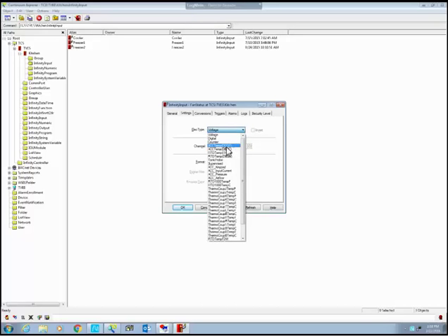A room temperature, if you want it in degrees Fahrenheit, and it is a type 3 10K ohm thermistor, you will choose the ACC temp degree F, and that should be fine for most all these thermistors that you get. I don't use counter so much. I know what it's for, but we'll get into that later. But if it's just an on and off point, you will choose digital. Okay?